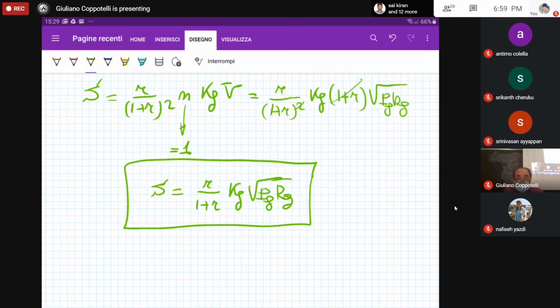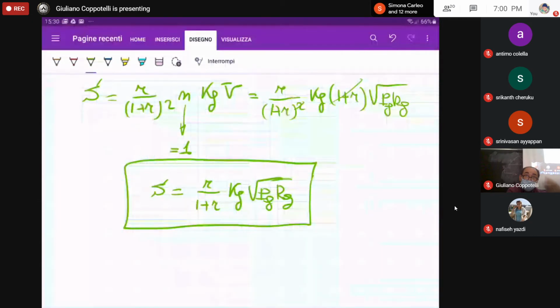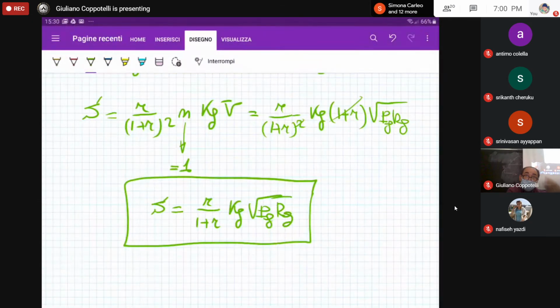Now we are having two strain gauges, but just only one active. The second one is only for temperature compensation. Now let's see what happens when you have two strain gauges that are actually measuring the same strain. So N will be equal to 2. Okay, so in this configuration, there could be a case where we want to compensate for the temperature. Instead of using, for example, the charts. Remember, how can you compensate for temperature?